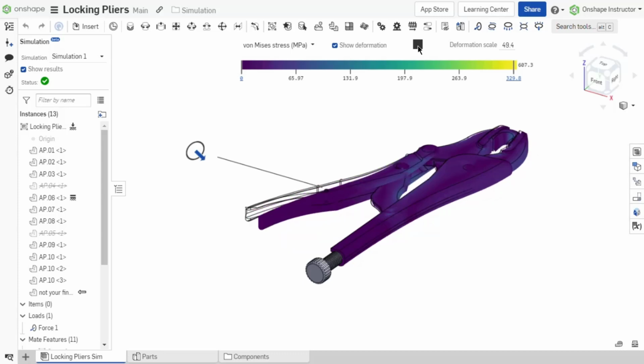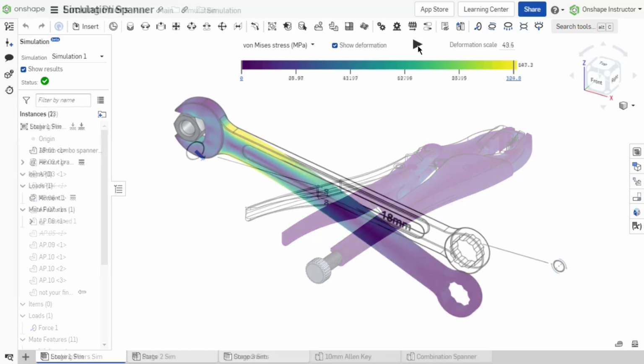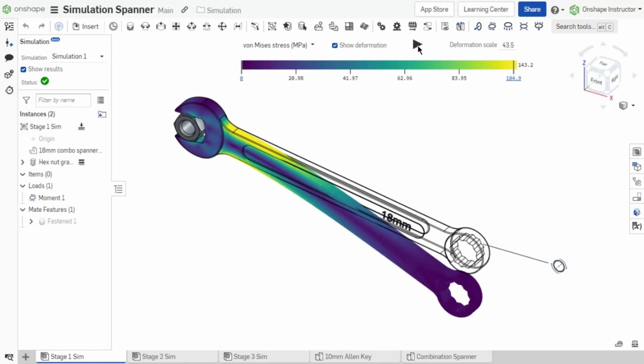By default, the force is distributed throughout the instance's volume. If a load region is enabled and specific faces of the instance selected, the force is distributed evenly over those faces. The moment load simulates the effect of an evenly distributed torque on an instance.